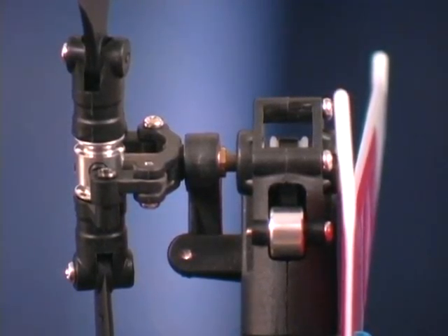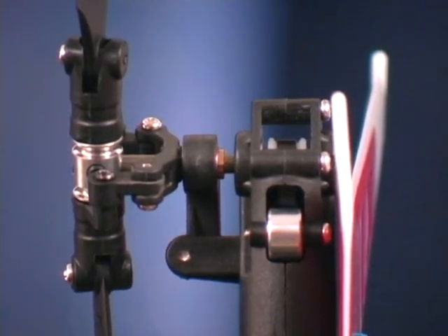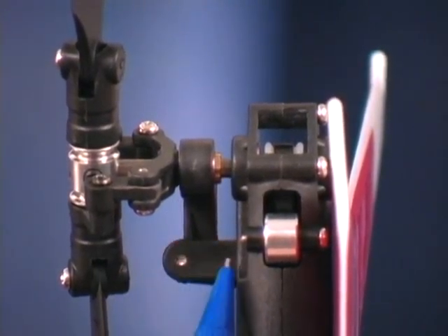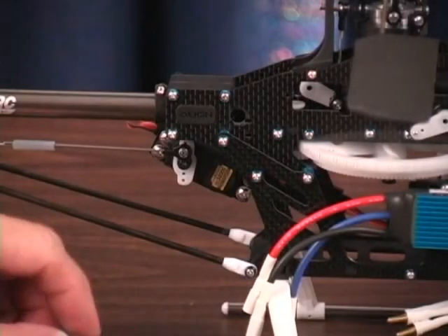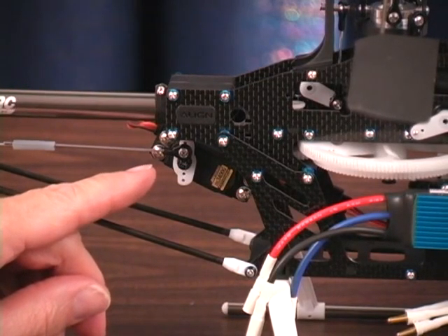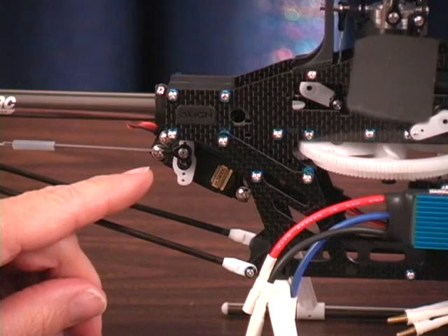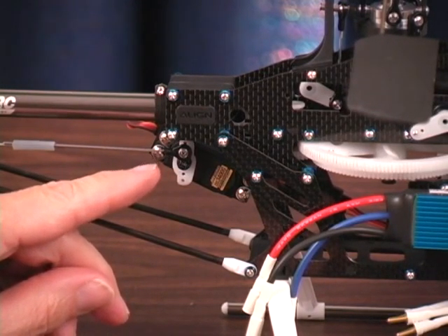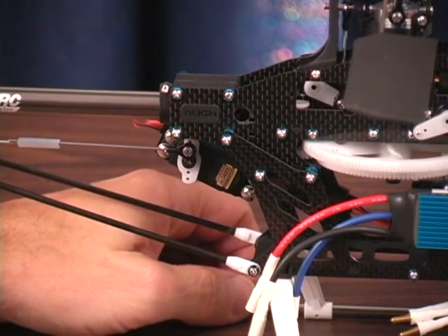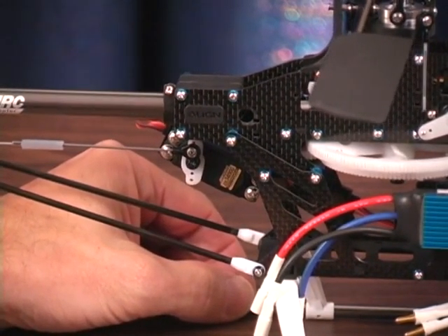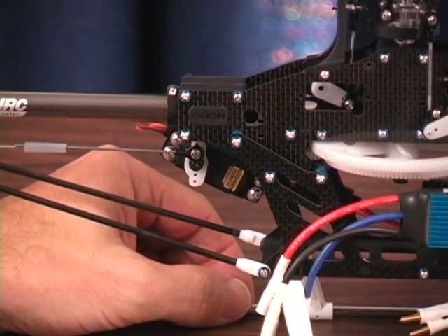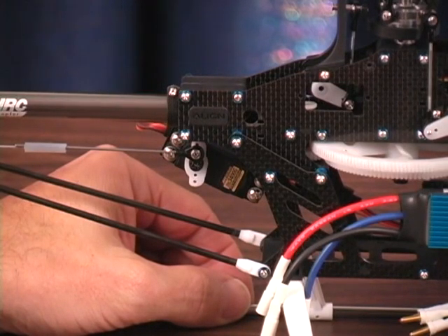This is a top view of the tail rotor gearbox, and here's an even better way to set tail rotor pitch. Just go ahead and set the bell crank 90 degrees to the standoff. Now let's see if the gyro works the right way or the wrong way. Again, right tail rotor moves forward, so when I yaw the helicopter to the left, the initial movement of the tail rotor servo arm ought to be forward. And here we go. Okay, the initial movement is aft to the rear, so the gyro works backwards. Let me go ahead and reverse the direction of the gyro.